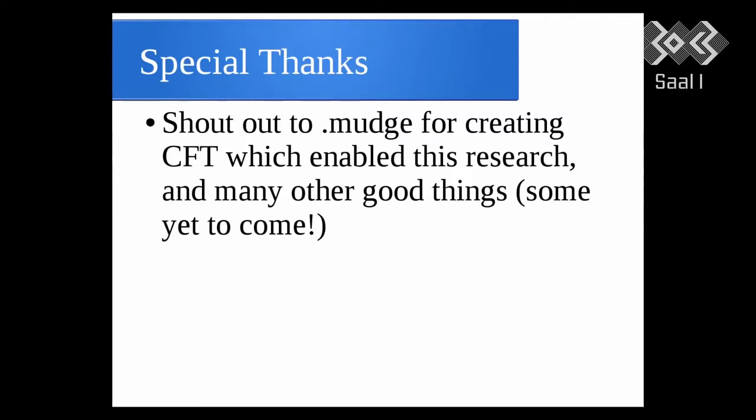And the thing is that if you can control the SD card, it is I/O limited, but it makes a great data logger. For example, you can go ahead and bit bang I2C or SPI and have a single chip data logging solution for €1, which is very exciting to me. We want to give a special thanks, a shout out to Mudge, who created the Cyber Fast Track program, which enabled this research and many other good things. Some are still yet to come. So thank you, Mudge.